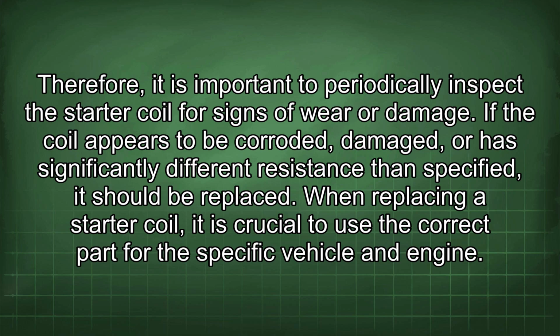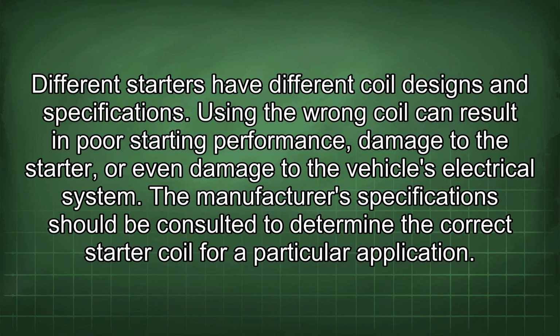If the coil appears to be corroded, damaged, or has significantly different resistance than specified, it should be replaced. When replacing a starter coil, it is crucial to use the correct part for the specific vehicle and engine. Different starters have different coil designs and specifications. Using the wrong coil can result in post-starting performance damage to the starter, or even damage to the vehicle's electrical system. The manufacturer's specifications should be consulted to determine the correct starter coil for a particular application.